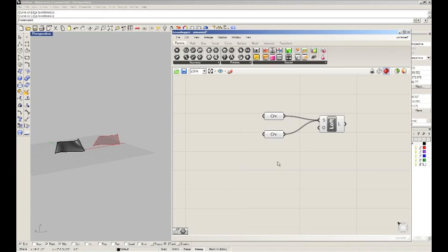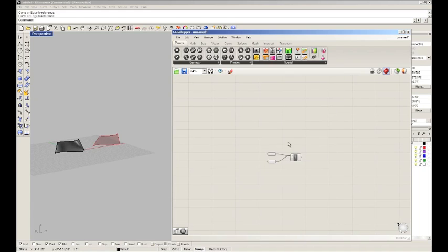Another thing to note is that Grasshopper is unitless. It's basically diagrammatic, and it deals with numbers. It'll count things, and it'll keep track of things in that way. But it pulls its units from Rhino. So whatever Rhino file you're working on, the units that are set as the base in that file will be the base units for Grasshopper.